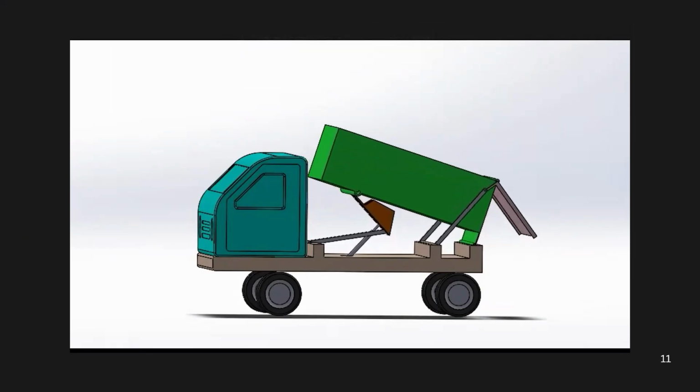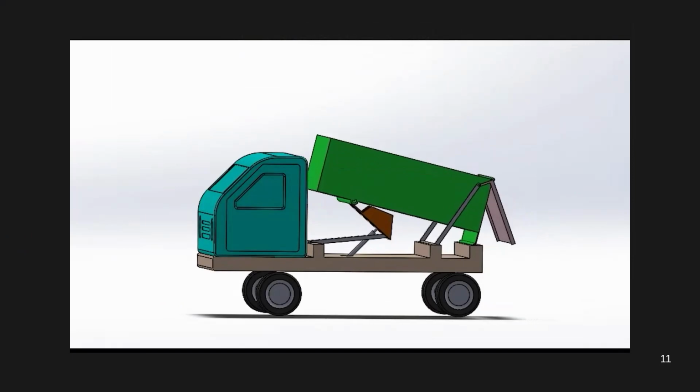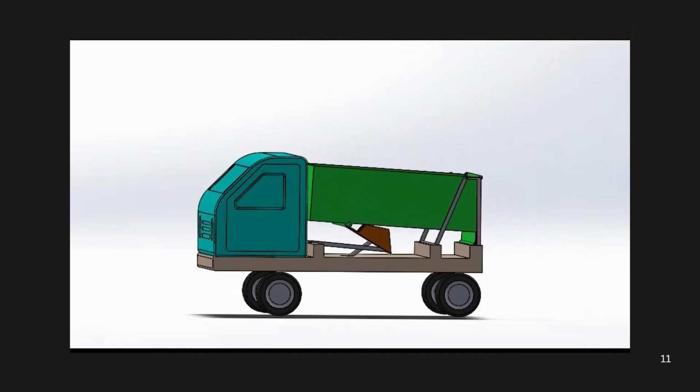In this project, we successfully designed and simulated a fully automatic door opening mechanism for a dumper truck using a combination of 5-bar and 4-bar linkages. The system ensures smooth synchronized motion between the bin tilt and door opening, eliminating manual effort and improving safety and efficiency. Our simulations confirm stable operation, no dead center locking, and reliable automatic locking when the bin returns to its original position. Overall, the mechanism offers a practical, low maintenance, and industry ready solution for modern dumping systems.